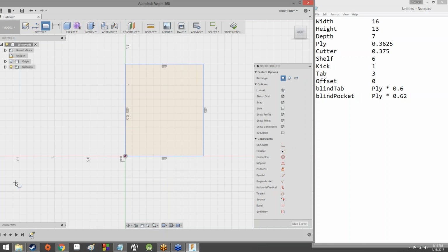And as you guys probably heard me say a million billion times as I was doing this, the size of the rectangle right now does not matter, because there are 2 aspects to sketching something in Fusion 360. They are creating the general shape, and then constraining them to specific measurements, because this is an engineering-based 3D modeling software.